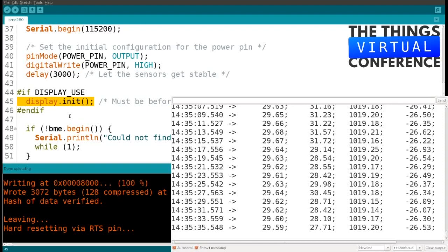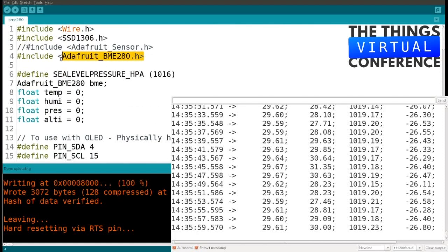So there are different typical places where you can make an error. If you work with more than one development board, you maybe have selected the wrong one under tools, board. Another case is the ID: if you use this Adafruit library, there is an ID in that file that can be different from the one you use in I2C.